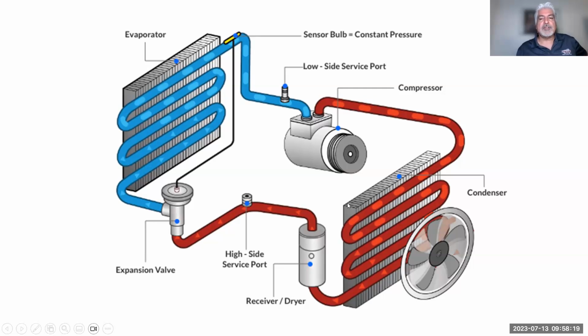But you can also have small leaks at the condenser as well. Since the condenser is exposed to the ram air that goes across it, it's been sandblasted, like here in the desert, or it's actually been hit with some kind of object where it could have a very small leak. Those are the ones that test you, because the problem is you're trying to find that leak. That's where I like the dye. The dye tends to work pretty good.